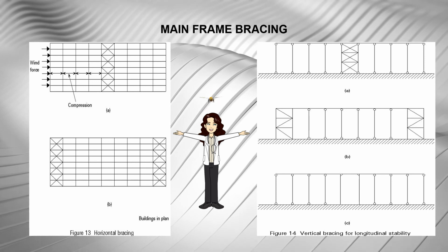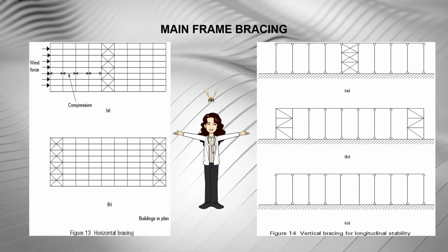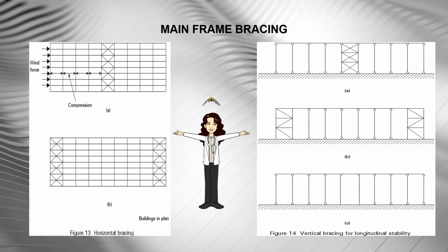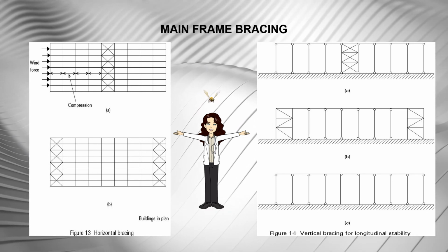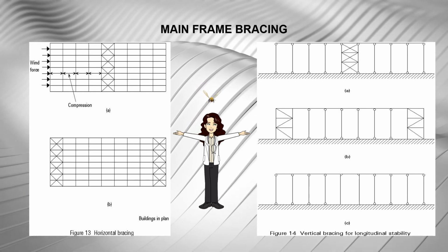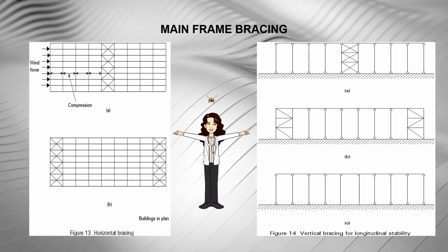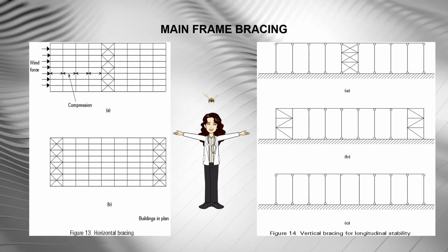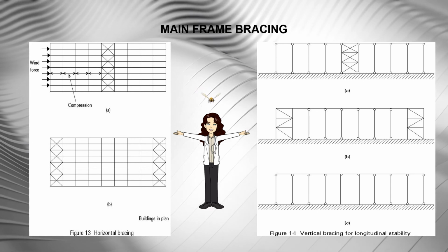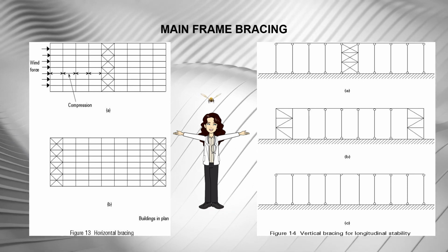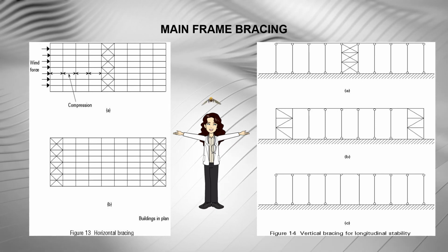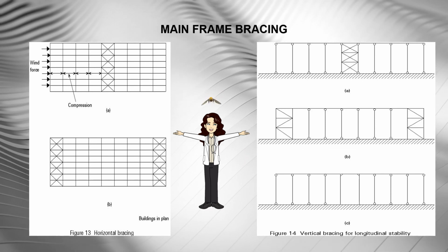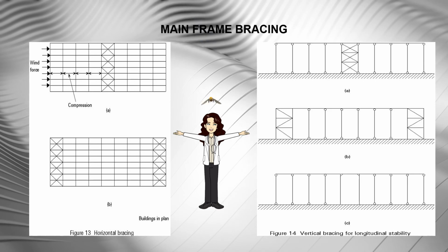Its disadvantage is that it prohibits the free movement of the building due to temperature, so that stresses develop in the members. By putting the braces at the mid-length, these disadvantages disappear since the building is able to expand freely. However, additional temporary braces should be provided during the erection stage to stabilize the first part of the building.